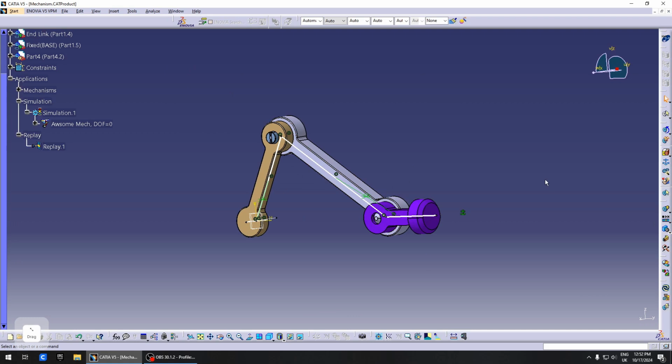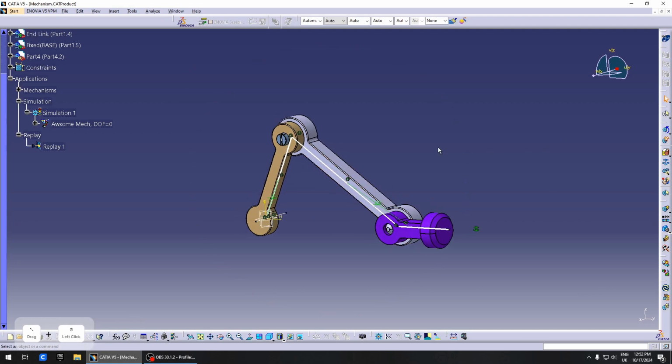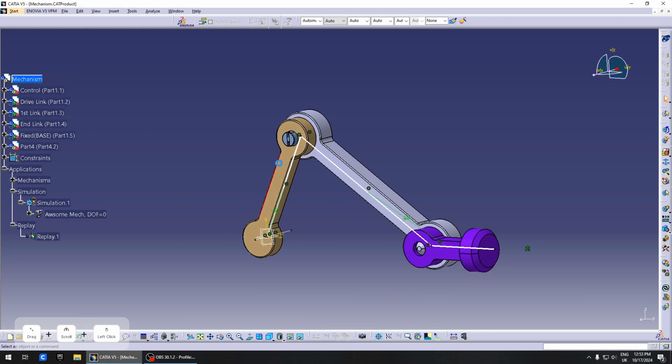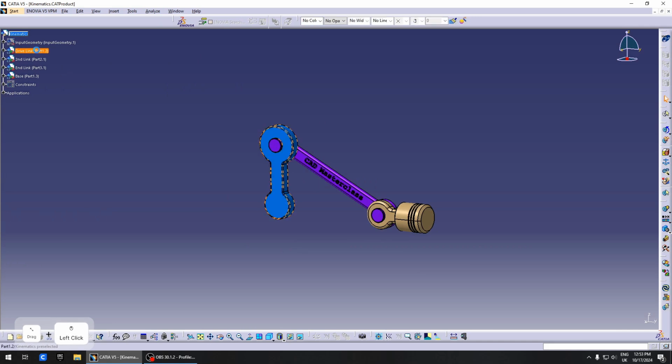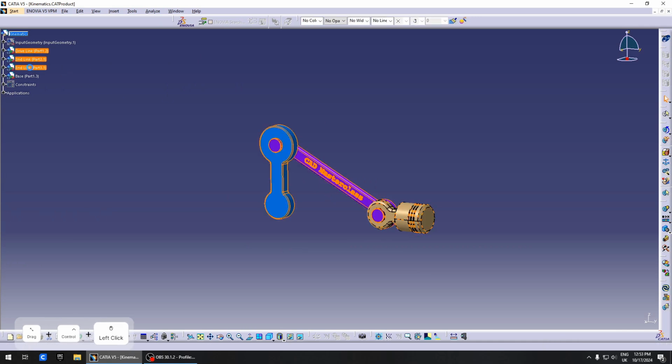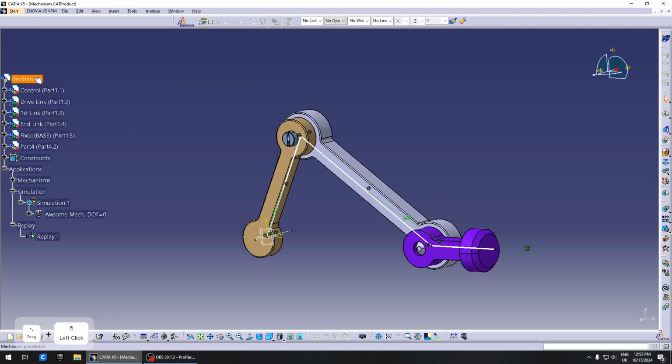So one other thing you can do in this module, you can dress up your mechanism. So let's say you have designed these links and you want to replace them somehow with a static part that's not linked to this, or even a linked one. It doesn't really matter. But you still want to have these parts connected to your mechanism. Let's say we're going to copy some parts from this product that I created offline before doing this. We're going to copy them here.